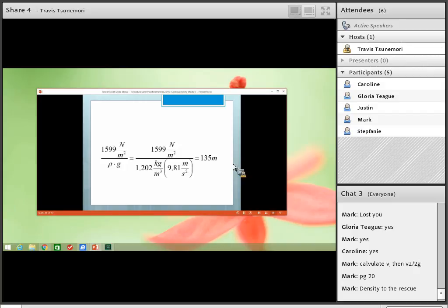Now I want you to look at the relative magnitudes again. Remember the expansion, the friction loss due to expansion was 21 meters. And the friction loss through the grain is 135. And that's only 1 meter depth of grain. So in a lot of problems, it makes sense to neglect some of the other terms and focus on the grain because it's going to be the major factor in your friction loss.